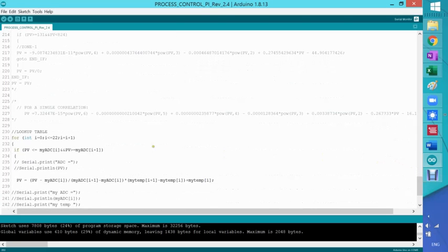So for the single equation, you can do the same. But now, in the single equation, that's interesting. I just plug whatever PV comes from the ADC, and it will provide a temperature. If the temperature is outside where this correlation was good, which was basically from -16 to 100 degrees, it was pretty good. It was plus minus 1 degree. Now, if you go above 100 degrees, you can have errors of about 4 degrees C.